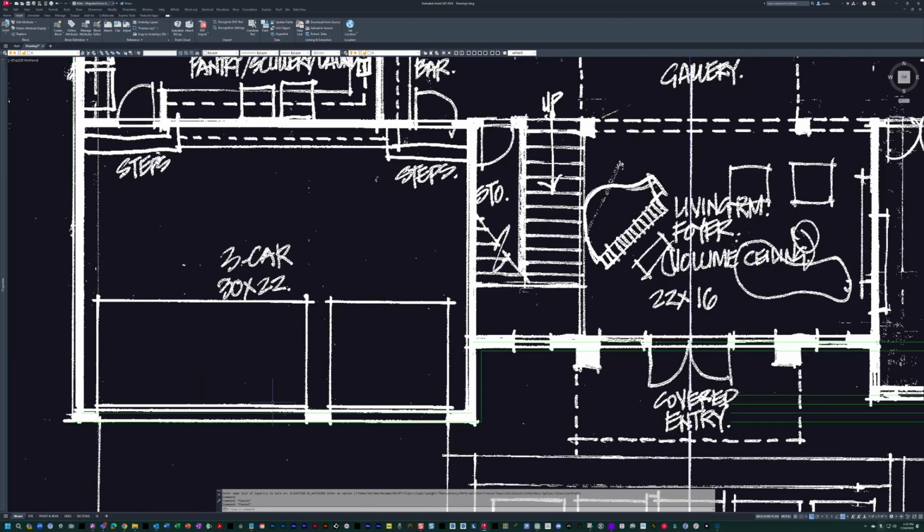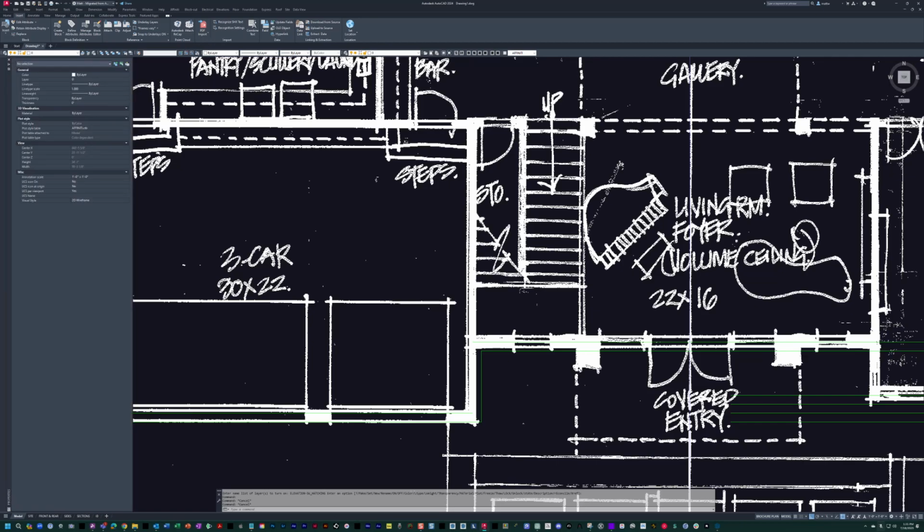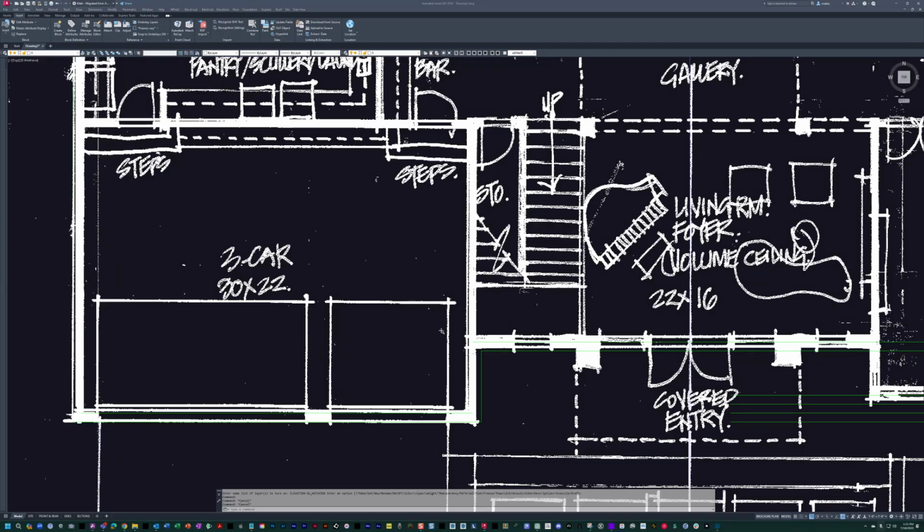And now we want to work on the verticals over here. So I want to add in an interior wall. So basically this interior wall right here. And we have two ways we can do it. On the inside, I definitely want to add a furring strip since this is a block wall. But in the garage, sometimes we do finished garages, other times we don't.